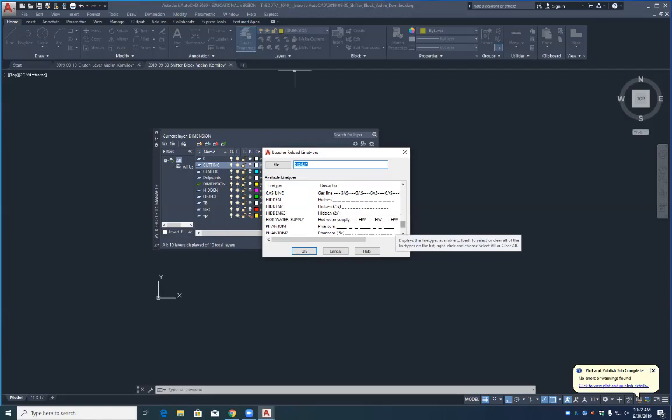Which one of those lines, either hidden or hidden times 2, looks double what hidden 2 is? Hidden times 2. Well, actually, be careful now. Look at the relationship. We want it double the size of hidden 2. Actually, the plain old hidden looks like the right one. Plain hidden, yeah. That's right. You see that? In the title, it says hidden times 2, but that is the line type we're going to be using for our section, our cutting plane. So I want you to click on that, just hidden.